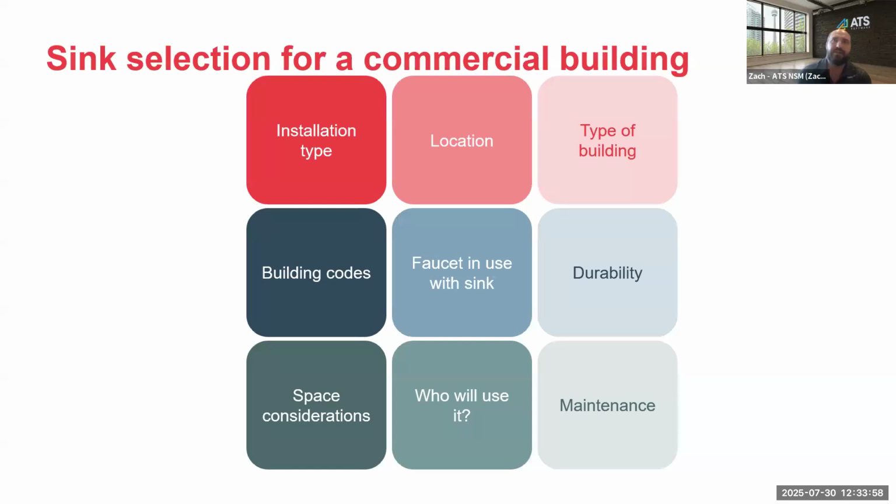I would also say temperature fluctuation is one of the points to very much consider. Molded stone and terrazzo are slightly more susceptible to massive swings in temperature. If you're going from boiling to very cold, if there's an application where that's coming in, that could be a cause for concern with any of the molded stone or terrazzo.